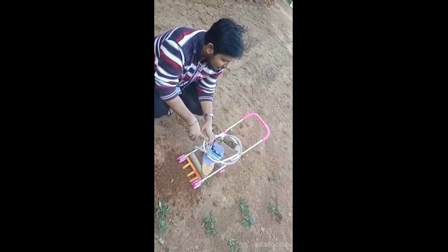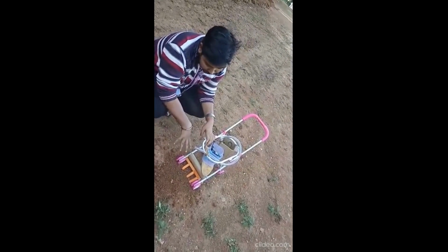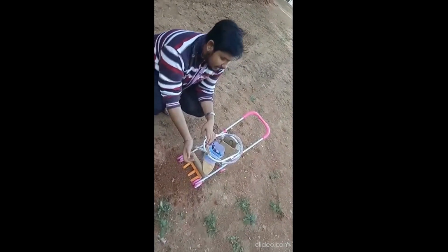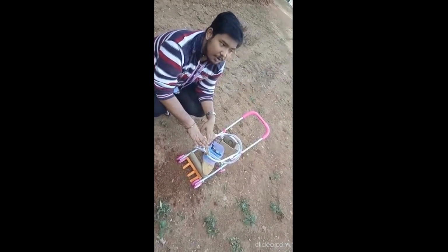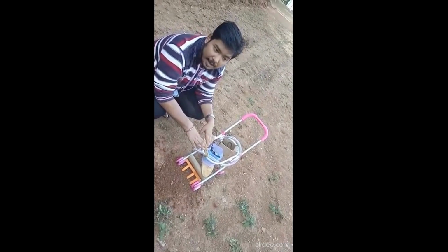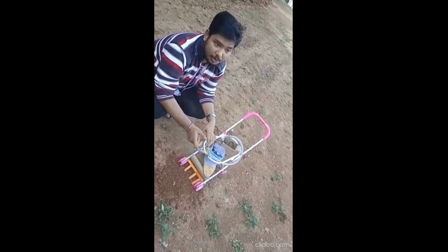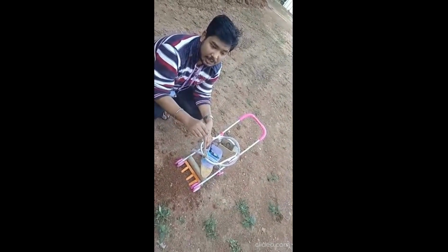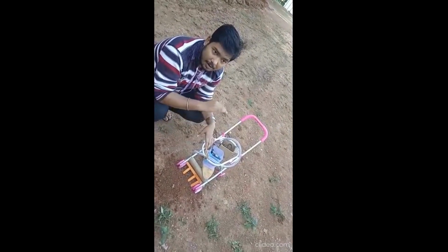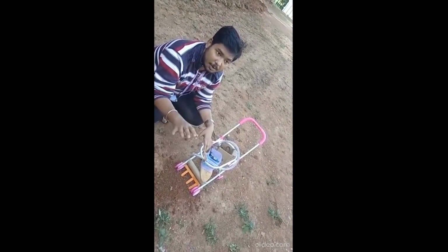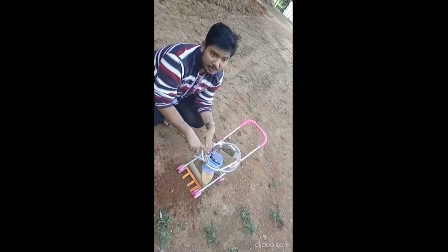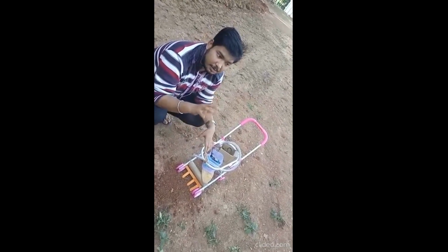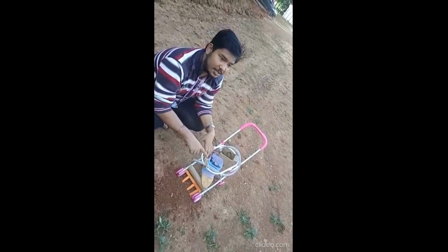Now, our vision is also to do this using a generator. The motion of the rotation of the generator will create output voltage. This output voltage will be fed to the rectifier, which converts it from AC to DC. This DC voltage will be fed to a capacitor for leveling out of the DC voltage and to obtain a positive steady voltage. Using a voltage regulator, since the voltage generated will be so high, this voltage will be dropped down and will be used for charging of the mobile phones.